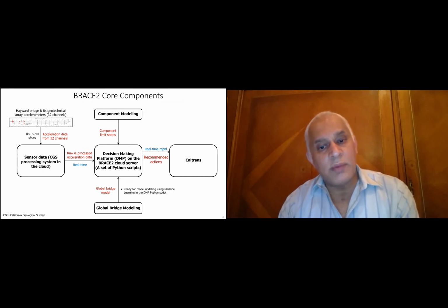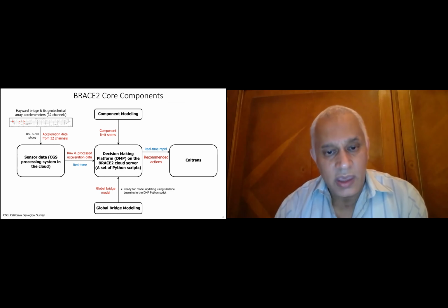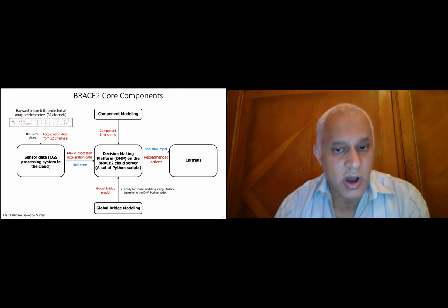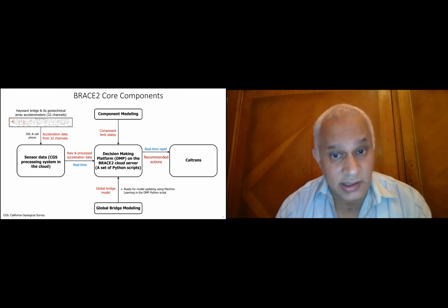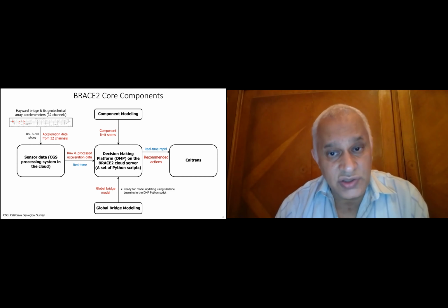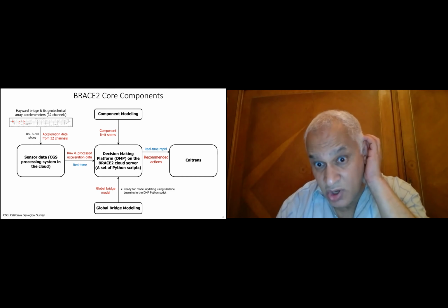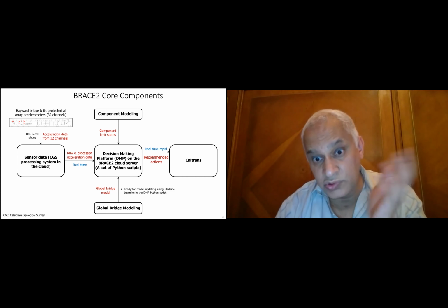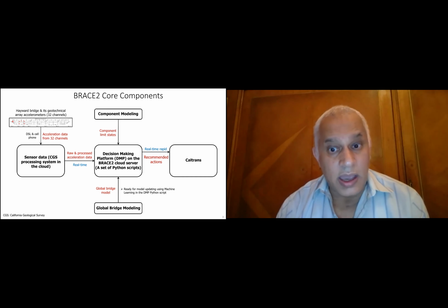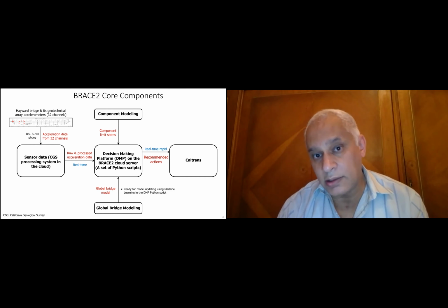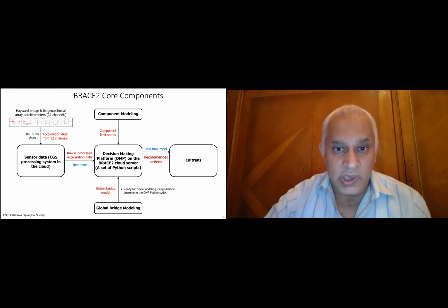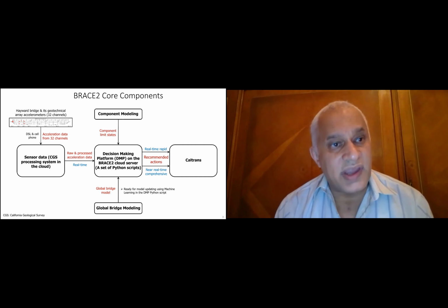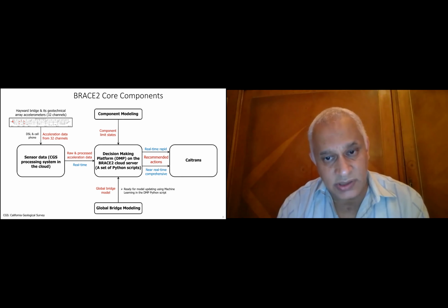If we want to do a more detailed modeling involving the global bridge model, which is ready for model updating using either conventional optimization to adjust the model parameters or using machine learning as part of this decision-making platform, then we can provide a more comprehensive assessment of the bridge response.